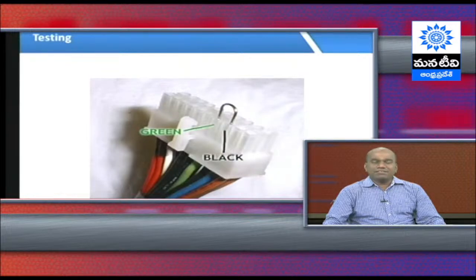Okay, give the power supply and check whether the SMPS fan is rotating or not. If it is rotating, half of the performance of the SMPS is good. To check the full functionality of SMPS, we need to connect the SMPS to the computer and restart the computer. If the computer has restarted successfully, then the SMPS is working fine.